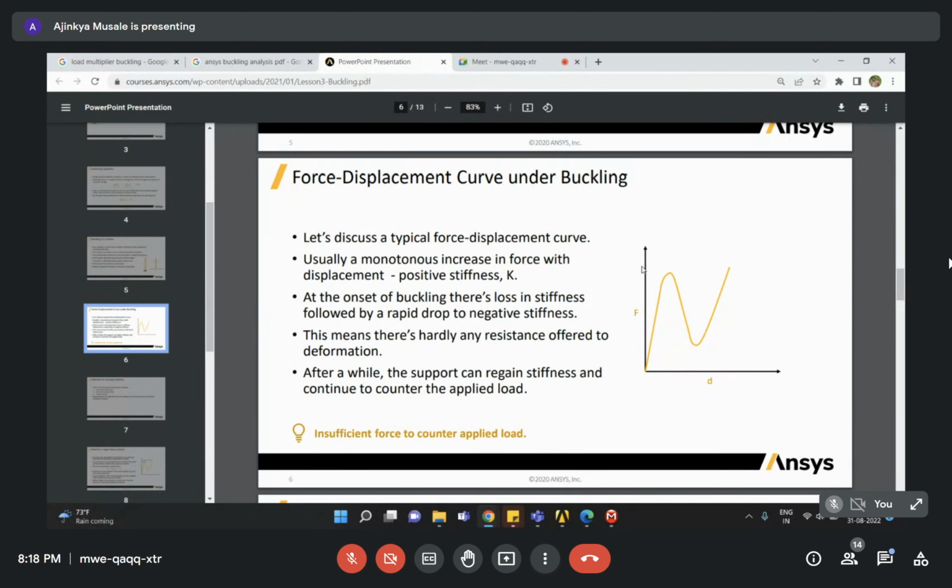So basically, my stress strain curve is something like this. It starts from the origin and goes until this point. Here my yielding occurs. Then it goes somewhat horizontally, and it will break. That's my general stress strain curve for ductile materials.